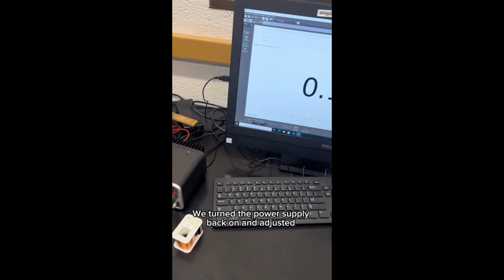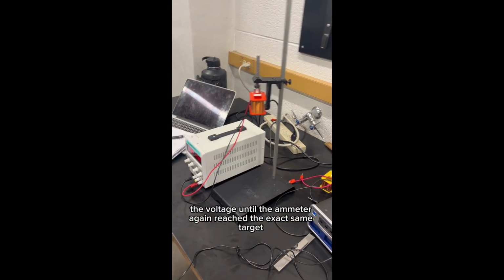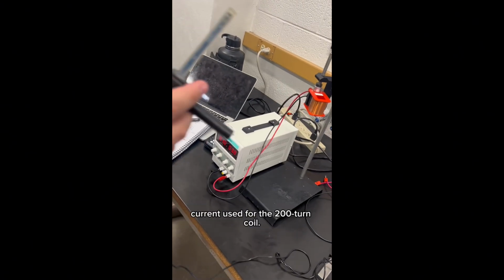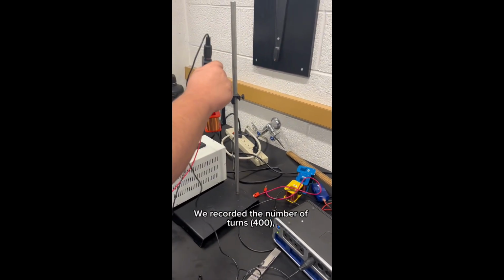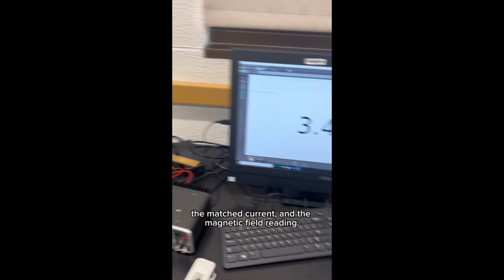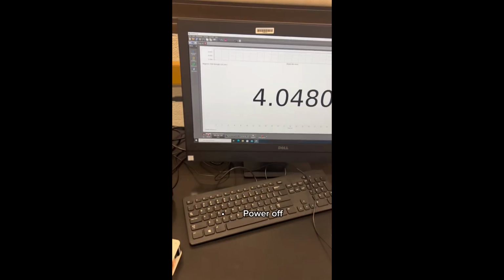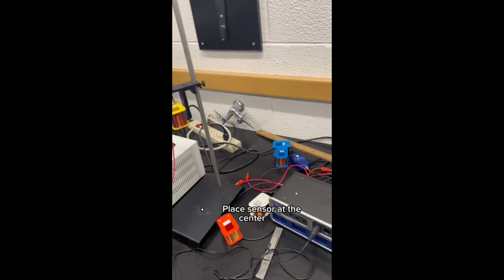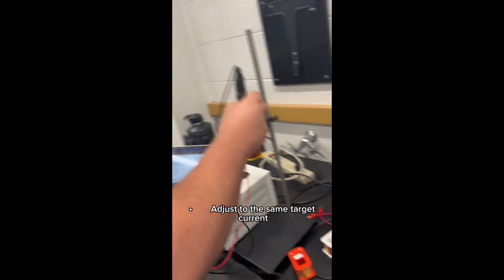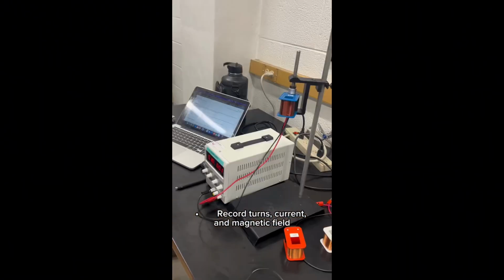We turned the power supply back on and adjusted the voltage until the ammeter again reached the exact same target current used for the 200-turn coil. We recorded the number of turns, 400, the matched current, and the magnetic field reading. We repeated this same sequence for the 800-turn coil. Power off. Swap coils. Place sensor at the center. Power on. Adjust to the same target current. Record turns, current, and magnetic field.